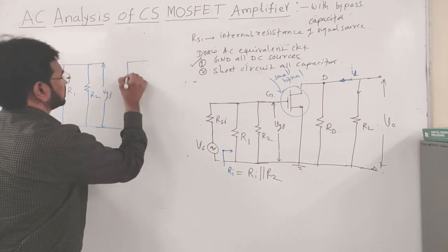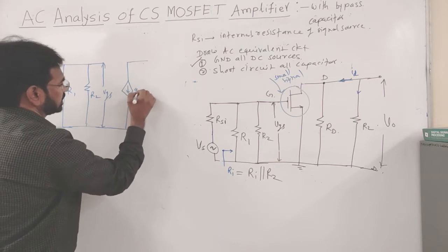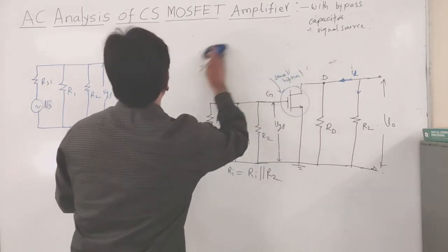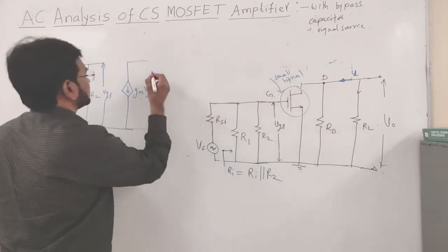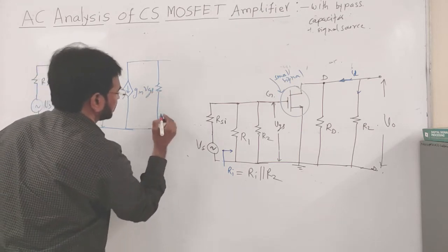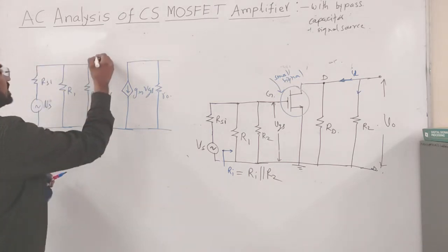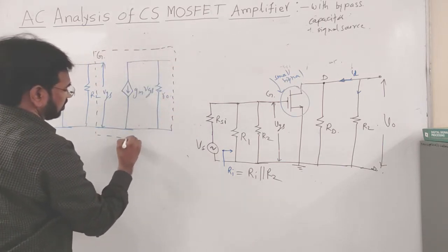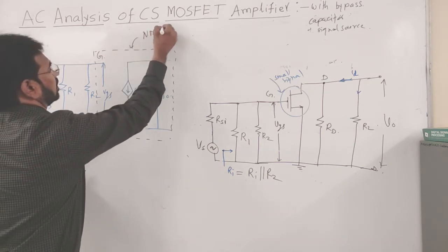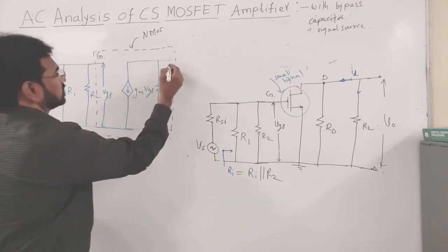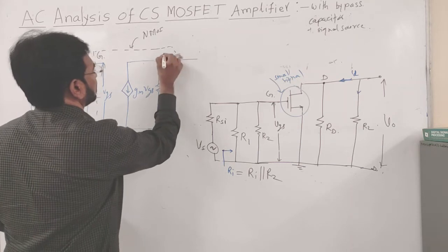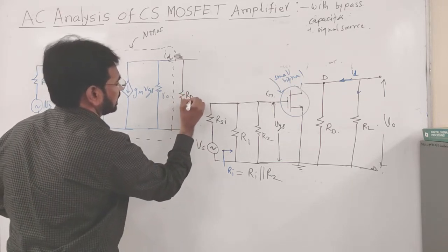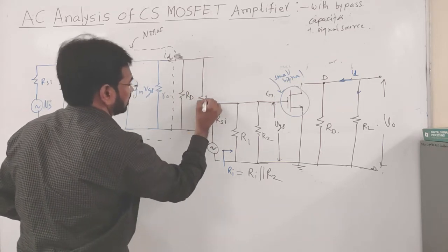and a current source. So, it is the current source here, and this current source is Gm times VGS, and here we have, what are the things remaining? RD. Okay. Sorry, not RD. So, it is the R naught, the finite output resistance of the MOS transistor. So, this represents the small signal model. This portion is the small signal model for the NMOS transistor. We have replaced the transistor symbol by using the small signal model. Okay. So, this is the ID, I can show here small d, and here we have the external resistor RD, as well as the load resistor RL parallel to this one.